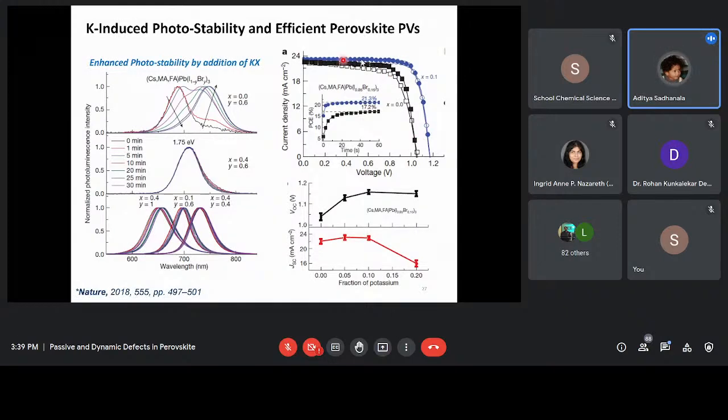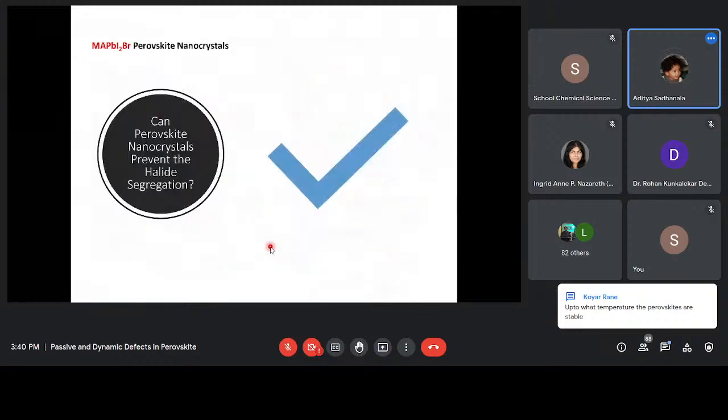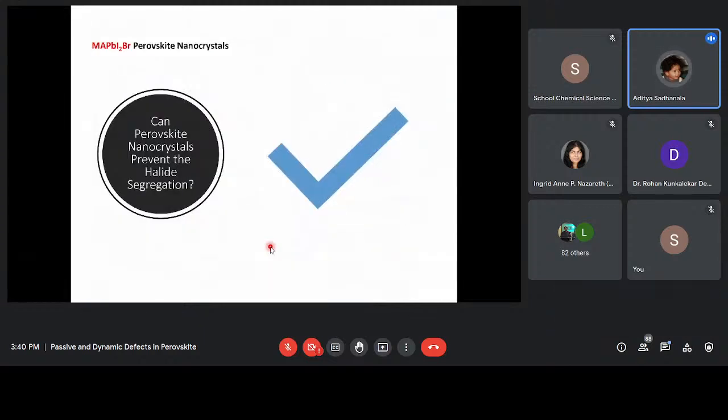So you see your control samples, this black curve is giving you this solar cell performance, and your voltage from your passivated sample, where the dynamic defect is not there, is giving us very high voltage. Okay, the same is seen here, and that is what gives you also very good performance. So you get almost 21% performance with these samples, whereas the unpassivated samples could give you only 17% efficiency. Okay, so that is one example.